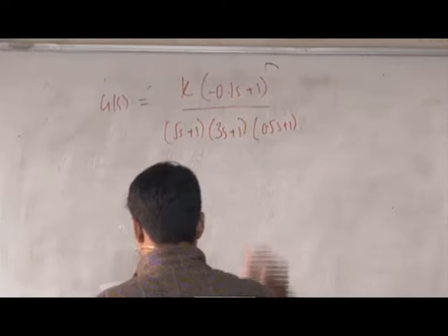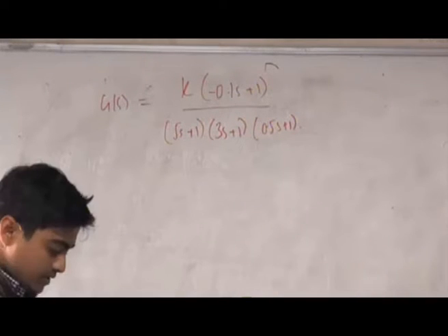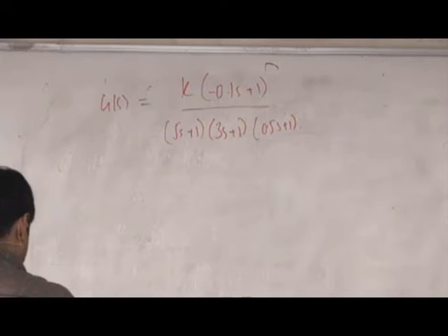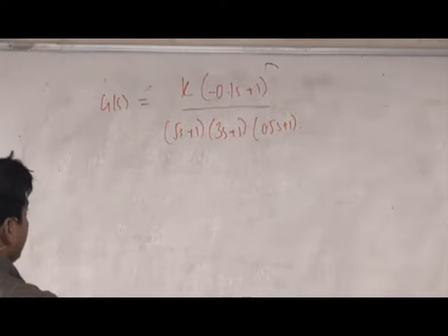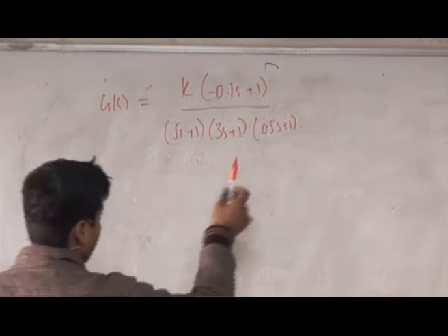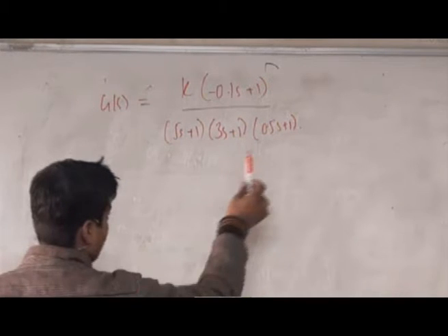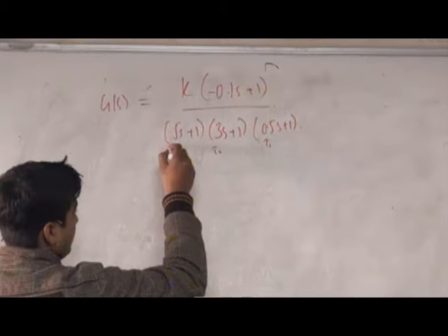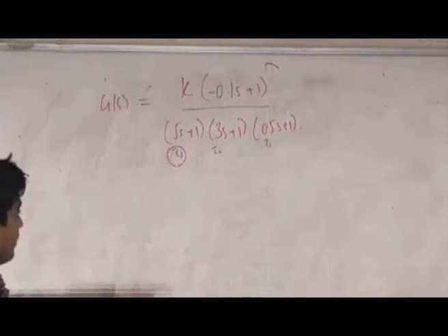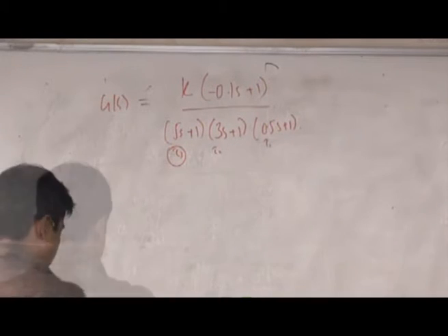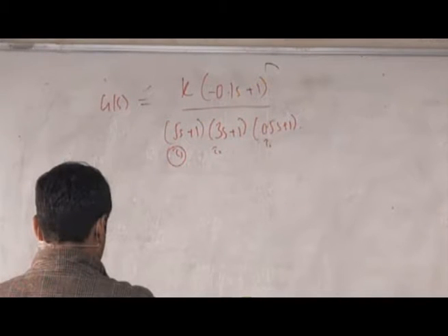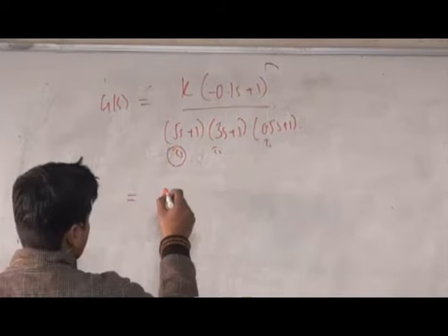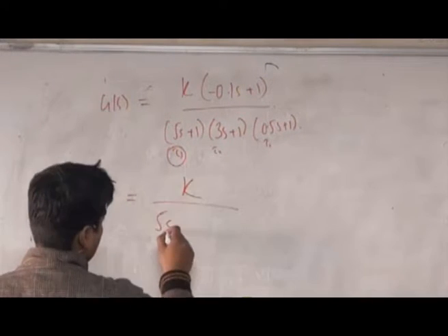The Taylor series expansion rule says to retain the dominant time constant, and among these time constants, let's call them tau 1, tau 2, and tau 3, tau 3 is the most dominant one. Why? Because of this, and approximate the rest of the transfer functions or polynomials. So I would retain this one.